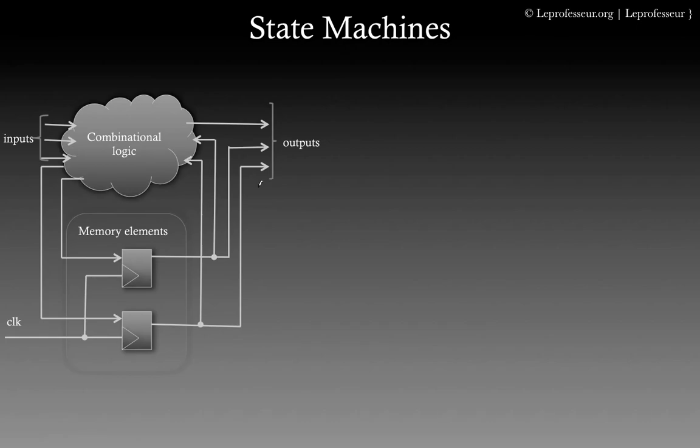No matter whether you have a smaller circuit or a bigger circuit, more or less you're going to be looking at these two blocks: one is combinatorial logic and one is sequential logic, where memory elements like registers, D flip-flops, or any other kind of flip-flop are used, but D flip-flops are the de facto industry standard. So we're going to be talking about D flops here.